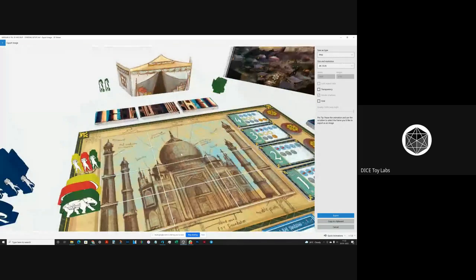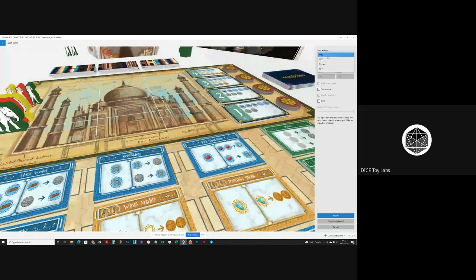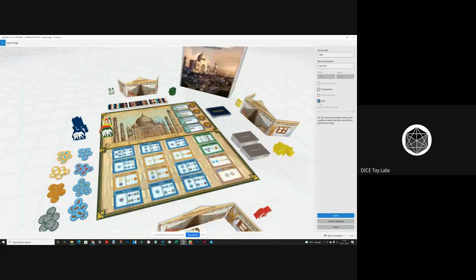Okay. So you can actually choose what kind of format you want, like PNG, JPEG, stuff like that. There are a couple of things I had to figure out by experimentation to see what is the best configuration to use to export a clean image. For example, you can put a grid and it says transparency here, but it doesn't actually save it transparent. It saves with a black background.